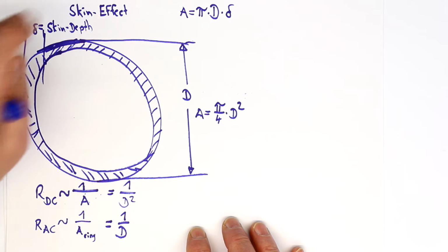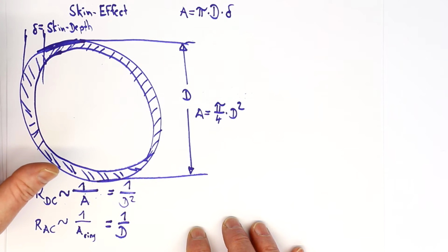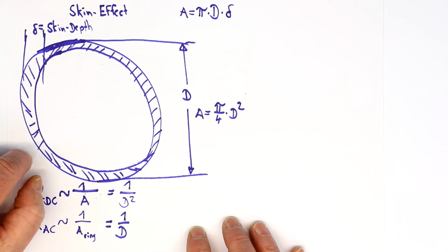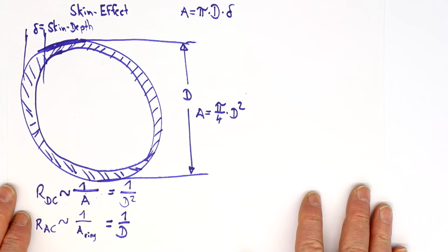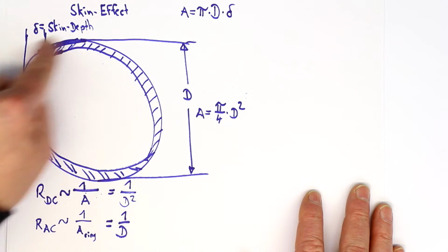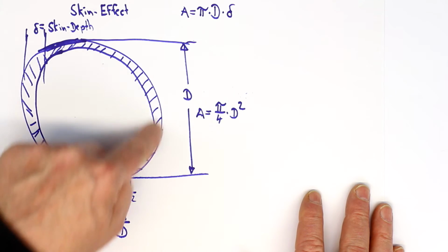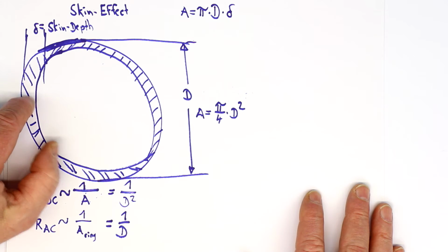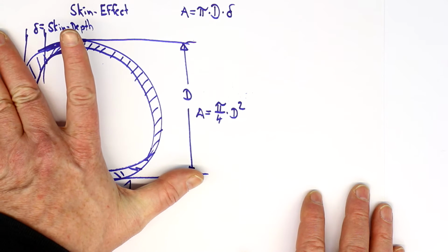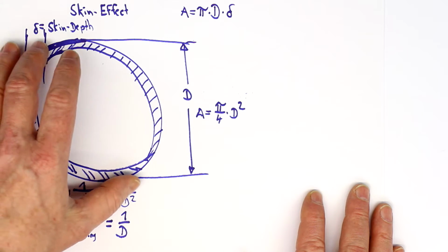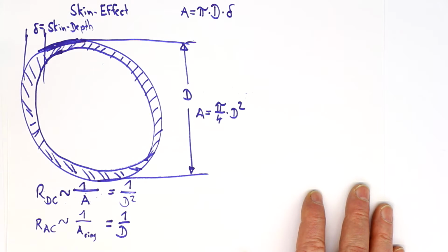And just so there are only two things to remember. The skin effect raises the ohmic resistance, so it's an ohmic effect, if we can call it that way. And when the current only flows on the outer layer, on a very thin outer ring, then we either have to enlarge the diameter of a thick wire, or we go over to copper tubing of the same diameter.